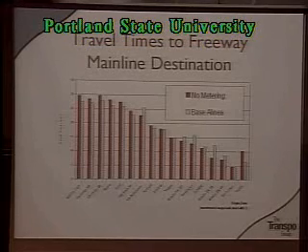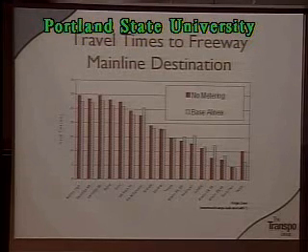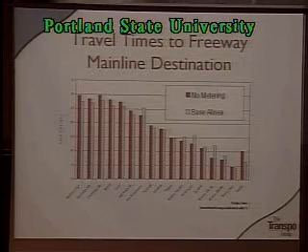And what you can see is that on the left side of this graph, these are the vehicles that are traveling the longest distances on the freeway. And because of that, the scenario with ramp metering is consistently better than without ramp metering. The opposite is true on the right side of the curve for shorter distances, because you spend additional time on the ramps and not so much gain on the freeway, so your overall travel time tends to increase in some cases.